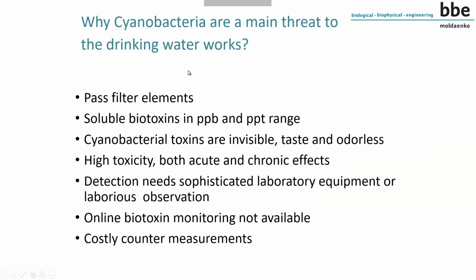All right. So what we hear from the people from the waterworks is: what do these biotoxins, this cyanobacteria, mean for them? Why is this a threat? Well, it could pass filter elements, for example sand filters. These biotoxins are not very well soluble in water, but in low amounts, in the ppb and ppt range, they are soluble and they can cause accidents and diseases.